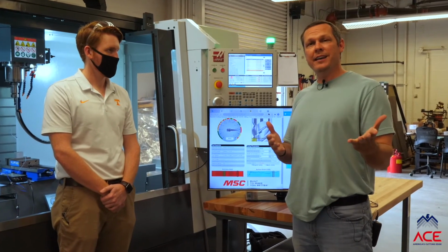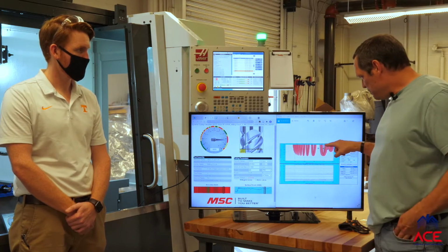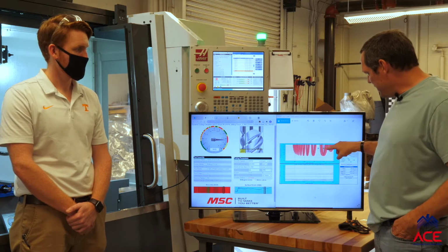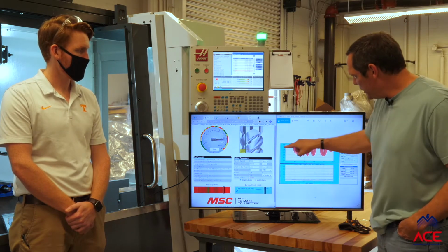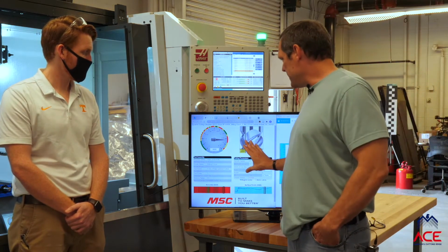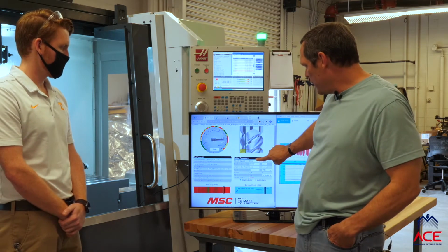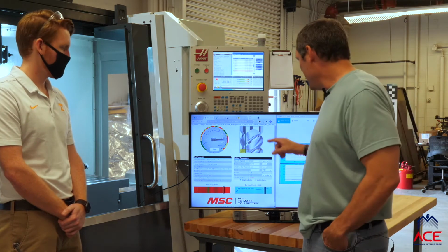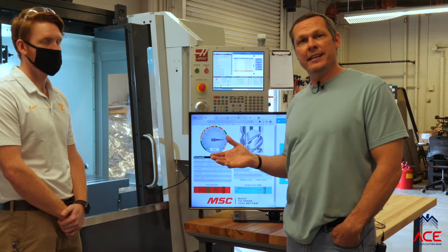Okay, so we're going to complete cutting tests now for 2 cases. The first case is we're going to select a spindle speed and axial depth which gives us chatter. And so we can see in this case for 6,600 RPM, we're in the red zone at a 20 millimeter axial depth, and we're predicting chatter. The same is true for the MSC MillMax dashboard. We have 6,600 RPM programmed, 20 millimeter axial depth, and then the 3 millimeter radial depth, and we're predicting chatter. We're in the red zone, and so we would have an unstable cut in that case.